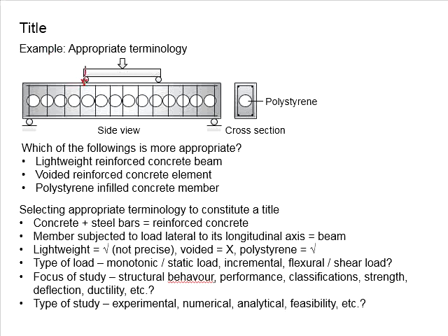And if you have this point load further away from the support, exceeding a certain range in terms of the distance by its depth of the member, the flexural failure of the member will be observed. Then you can address that as the flexural load.